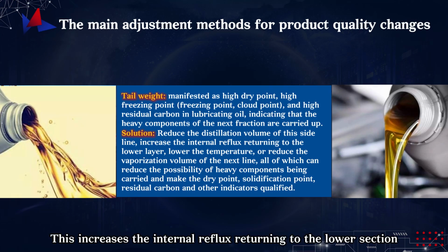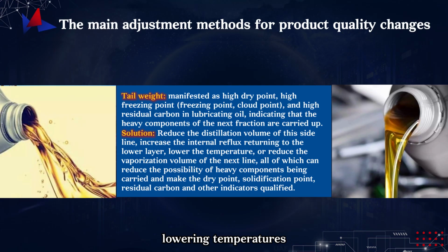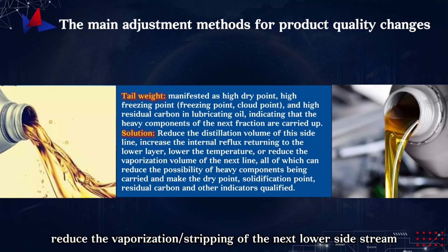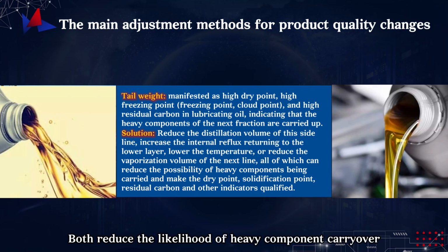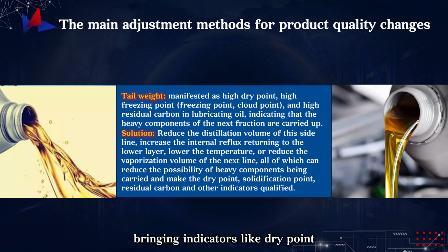This increases the internal reflux returning to the lower section, lowering temperatures. Alternatively, reduce the vaporization or stripping of the next lower side stream. Both reduce the likelihood of heavy component carryover, bringing indicators like dry point, pour point, and carbon residue back within specification.